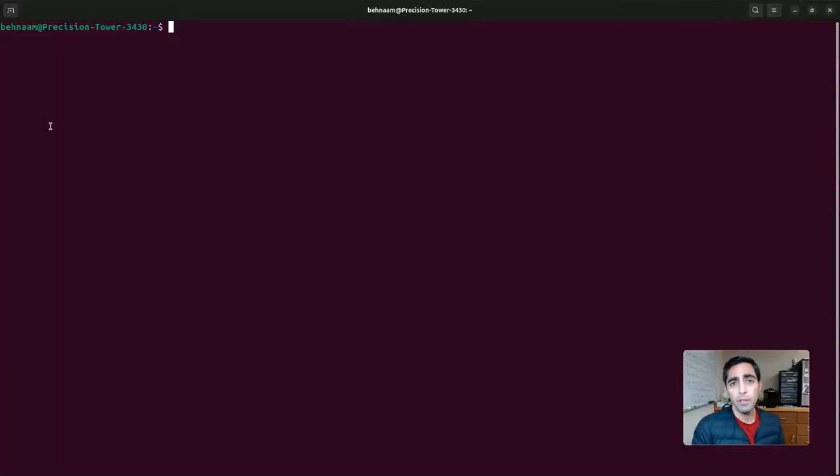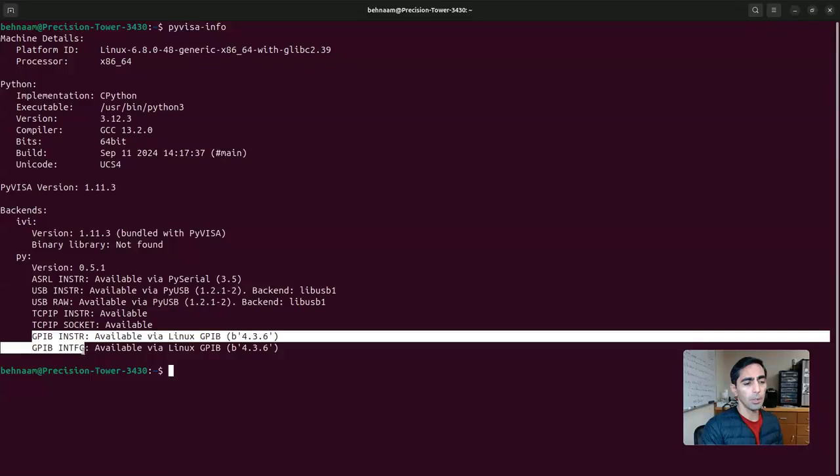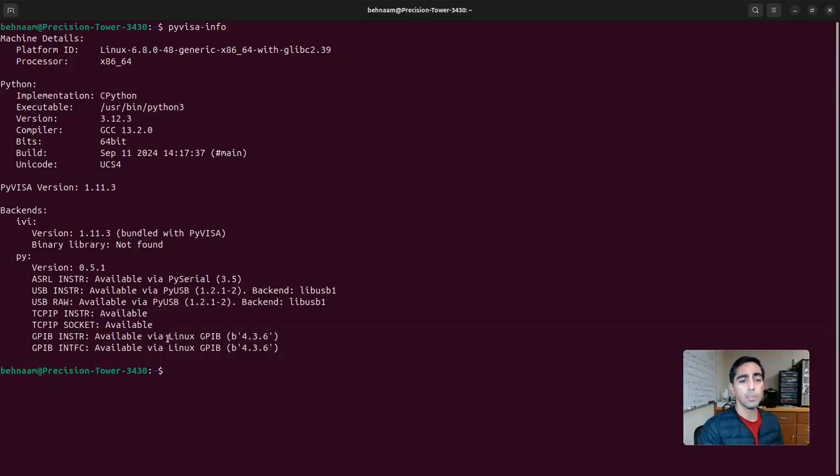Hello there. Before starting part 3 of this video series, let's give a quick recap of part 1 and part 2. In the first part, we were able to successfully set up the Pi backend of the pyvisa library, and we can verify that by running pyvisa-info. And as you can see, the Pi backend is able to access these GPIB resources through the Linux-GPIB package.